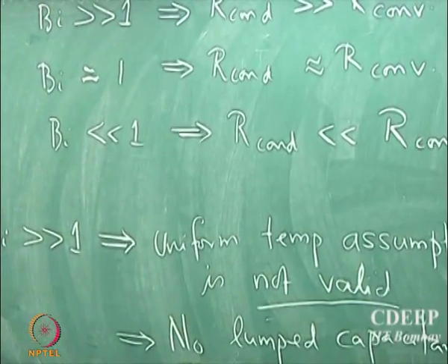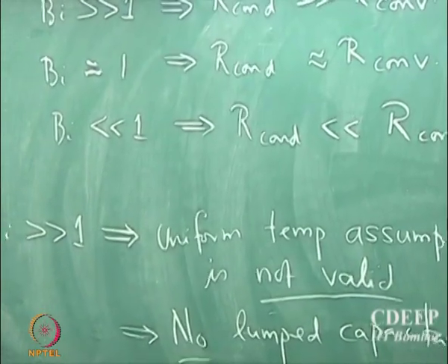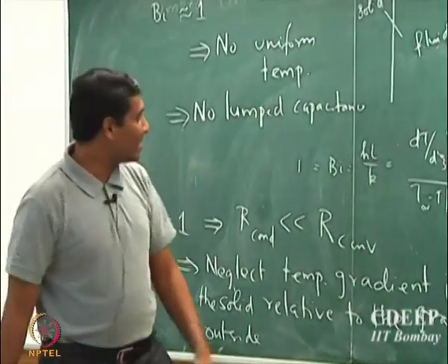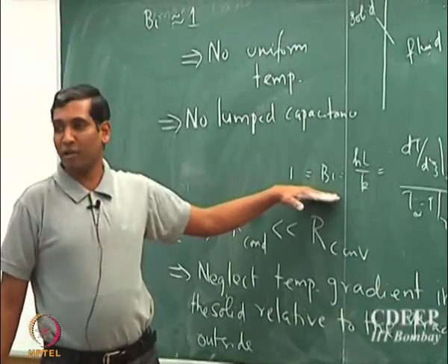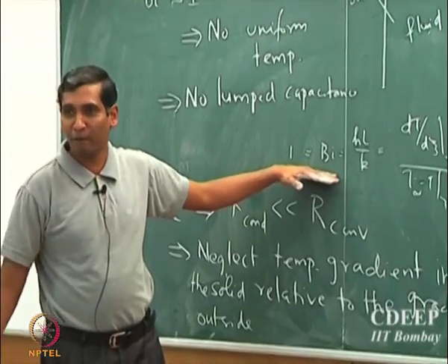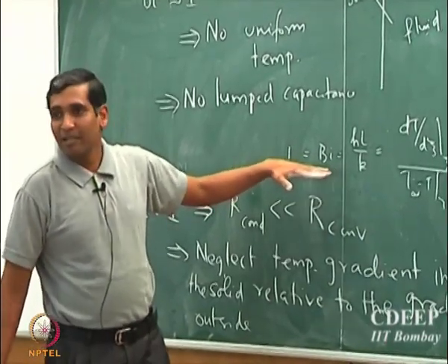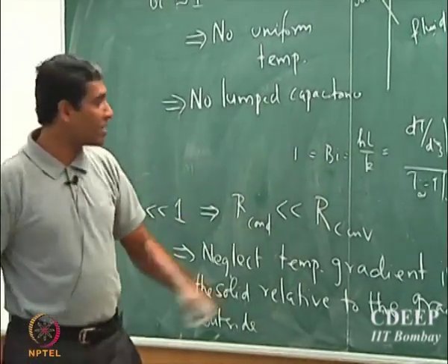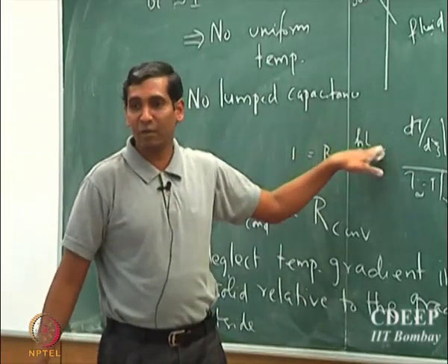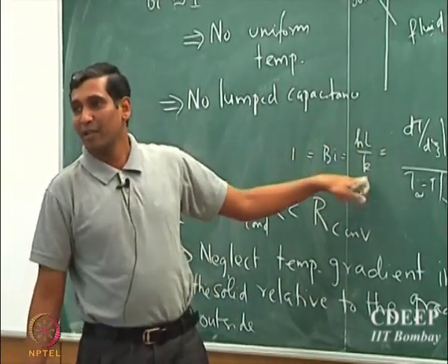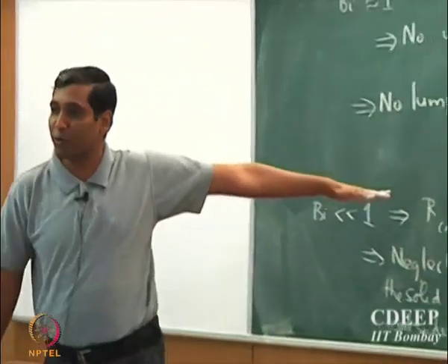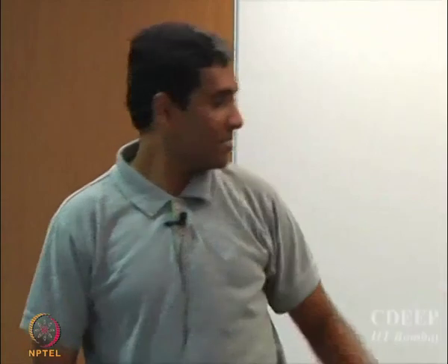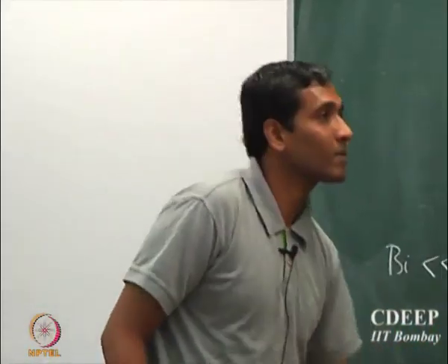So instead of looking at the heat transport coefficient, length and the effect of conductivity individually, it is enough to look at the variations of the features or properties of the temperature with respect to the Biot number, which actually captures all the effects that are included in the heat transfer coefficient, length and the conductivity. So this is the elegance that you get by defining a dimensionless quantity. Any questions so far? Okay.